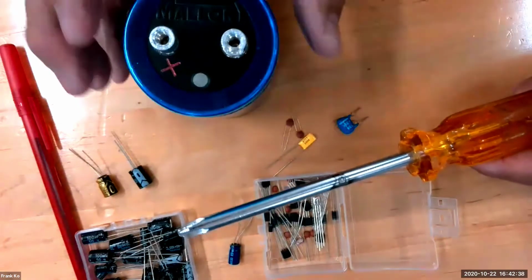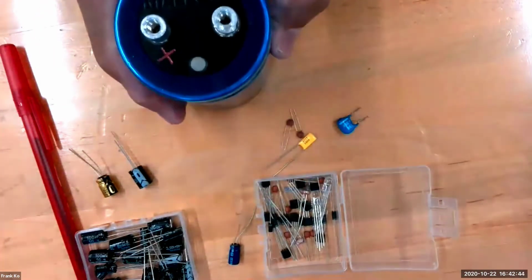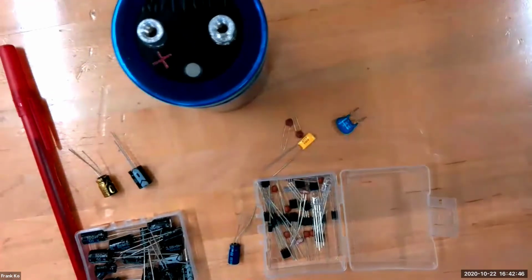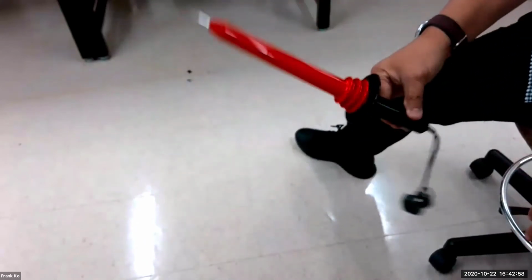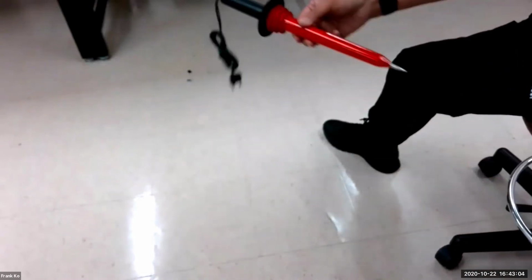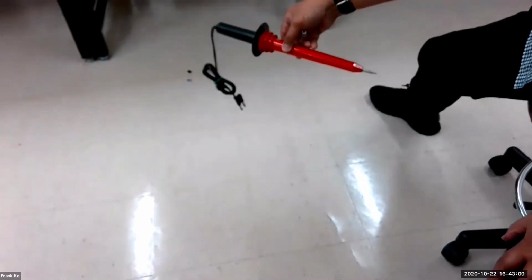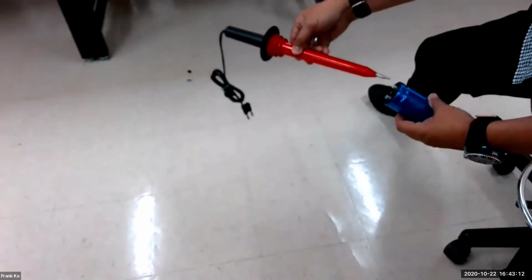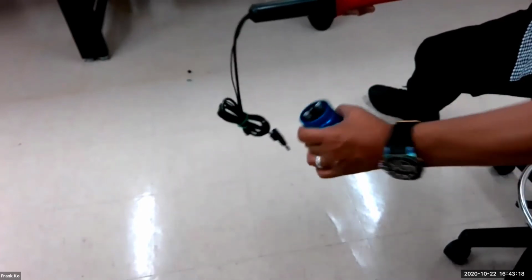All right, there is a method by which technicians can safely discharge electricity from a capacitor, and that method is done with one of these guys. Let me hold this out here so you can see the whole thing. It looks like a cattle prod. It's used for discharging a capacitor. The metal tip is what's used to touch one side of the capacitor, and on the other side of the capacitor, we would have this cable touching the negative side.